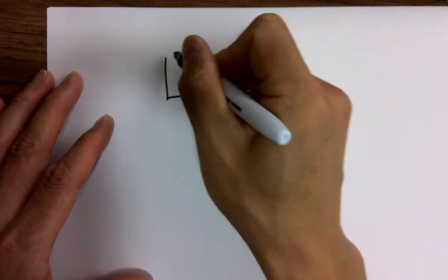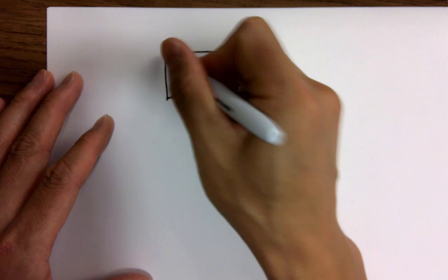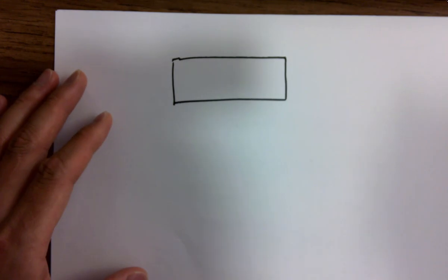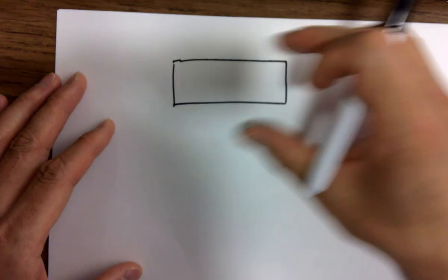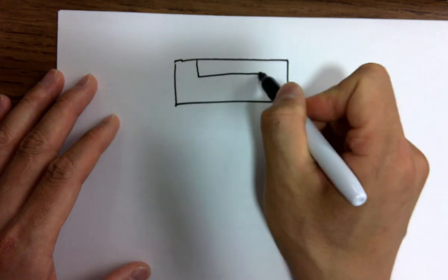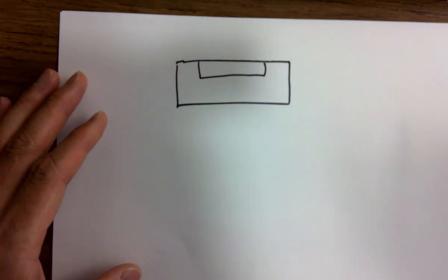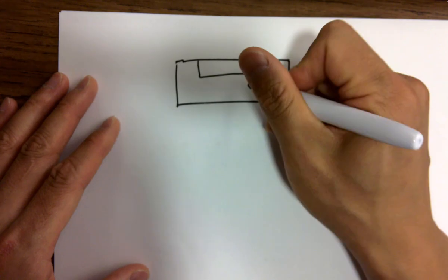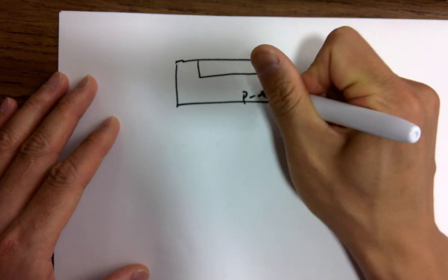This is related to the lab from last week and also this week. We have been doing N-well resistors, and you probably don't know what an N-well is. If you look at the wafer from the side, this is a cross-sectional view of the wafer. It's actually really thin, but I'm just drawing it to make it visible. So the N-well is just N-type material being doped into the wafer. Usually this wafer's material is P-type, for example.